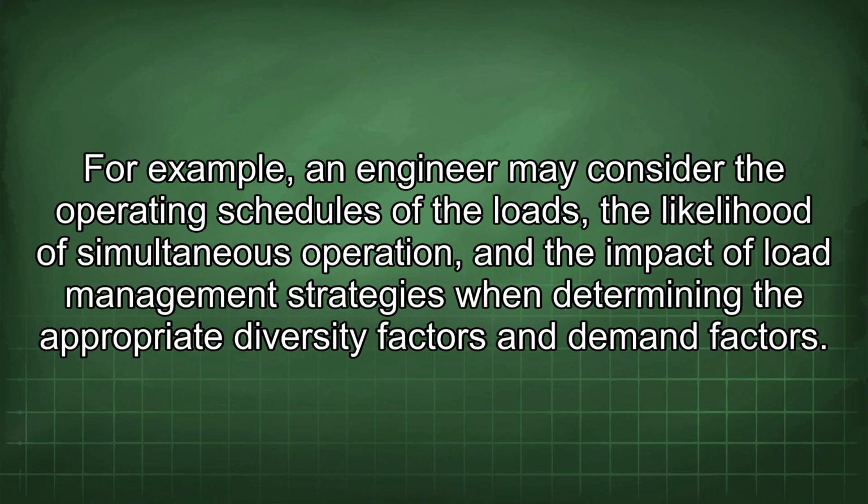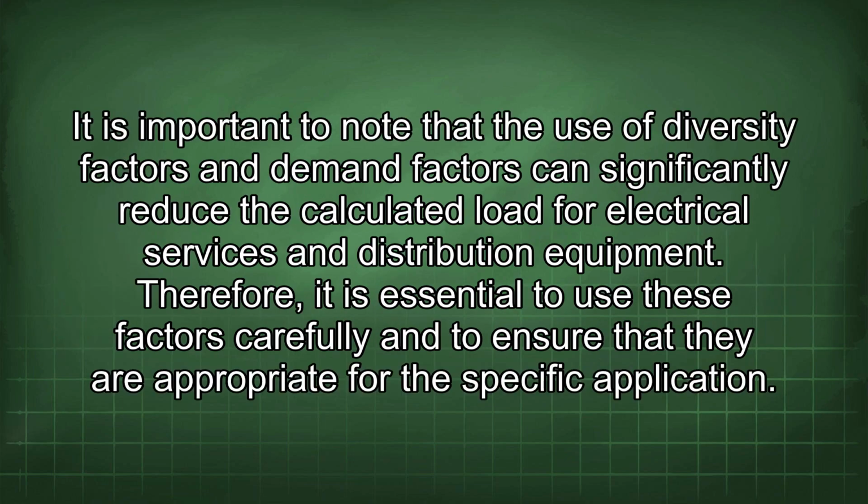For example, an engineer may consider the operating schedules of the loads, the likelihood of simultaneous operation, and the impact of load management strategies when determining the appropriate diversity factors and demand factors. It is important to note that the use of diversity factors and demand factors can significantly reduce the calculated load for electrical services and distribution equipment. Therefore, it is essential to use these factors carefully and to ensure that they are appropriate for the specific application.